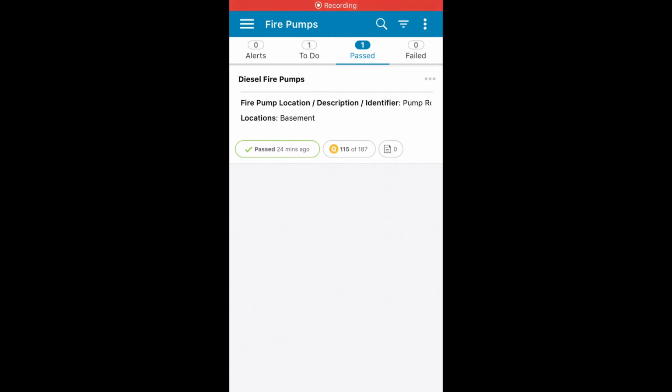In this video, we will be testing a fire pump using the flow meter loop, which we can use 2 out of 3 years for our fire pump inspections if it's available. We'll also be going over eliminating the 50% test as a simple click of the button to get rid of that test if you're not using a 50% test, and it will not show on your graph or on your report. Let's start off by going into our question bubble there with 115 of 187 questions.